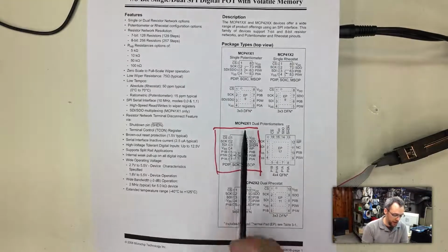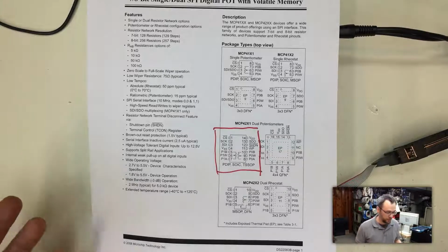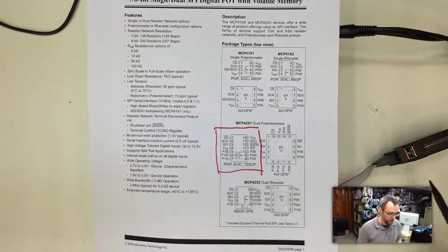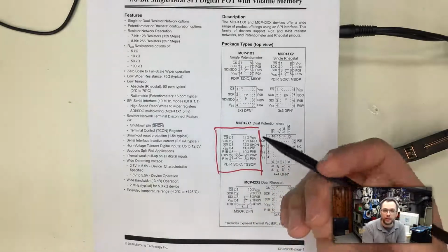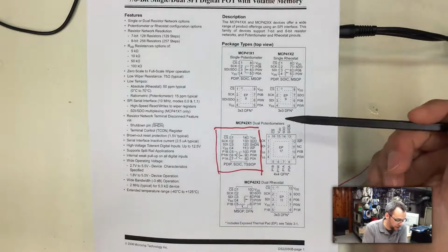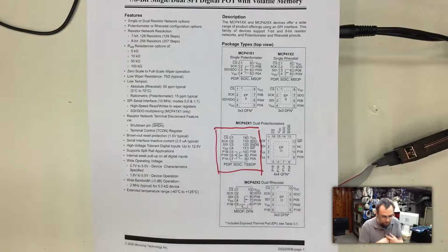Now, every SPI device is going to have different meanings for what all those bits are going to mean, obviously. And this guy's no exception. He has his own command and data bytes that you have to send it. It has specifications that it has to receive 16 clocks before it takes valid data.